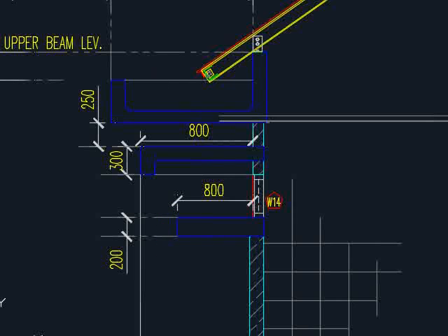You will have to imagine how you're going to reinforce this RC gutter, as well as how you're going to keep this in place. It cannot be simply attached to the brick wall, as the brick wall is non-load bearing, and you see the extensions of the member from the brick wall. It would behave as a cantilever.